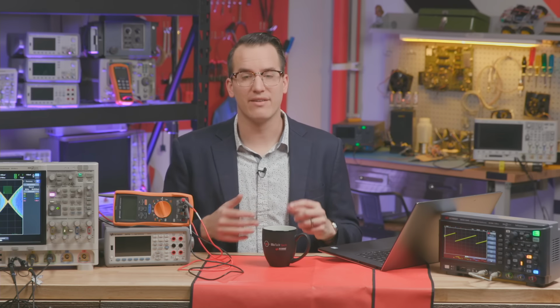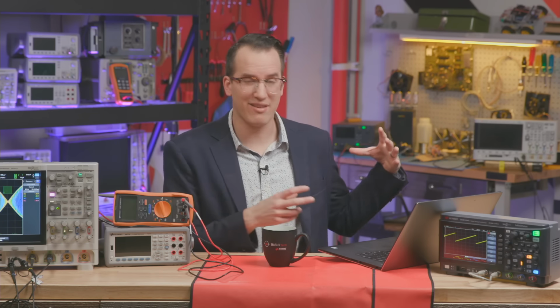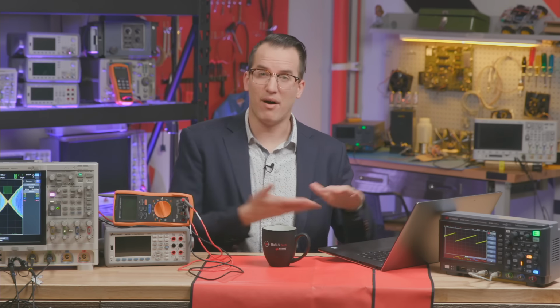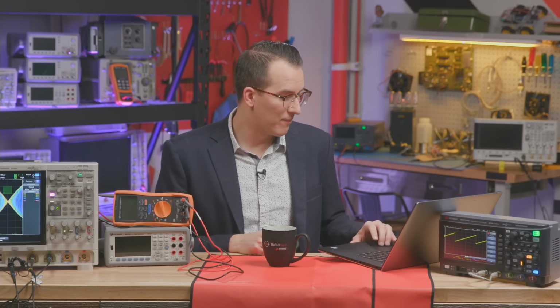The thing that a DAQ does is the sample rate is very, very high and very, very consistent. With a microcontroller, it's not always as reliable and your sample rate's gonna be lower. Also with a DAQ, you can get things like multiplexer modules. One of the things that you saw in that prize clip from earlier in the video is those modules that slide in the back. The flexibility with the DAQ is it's very flexible compared to something like a Raspberry Pi. So that's the main difference.